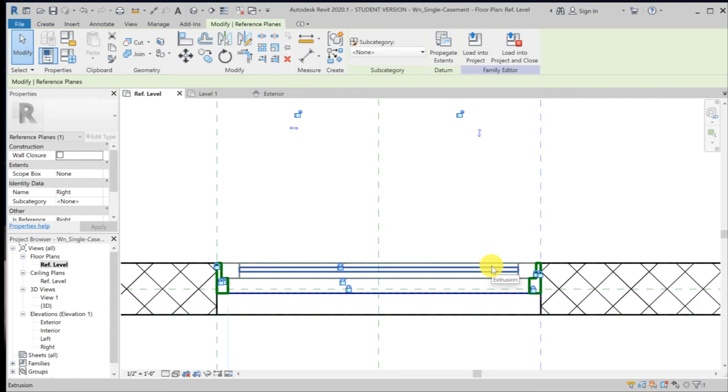Okay, so I'm going to take a different approach here compared to the door. With the door, I made the swing adjustable, but in window family or in the graphic symbol that we use for window in plan view, we never show them in full 90-degree open. We usually show it somewhere between 15 and 45 degrees. So I'm going to be somewhere in the middle. I'm going to show it fixed at 30 degrees.